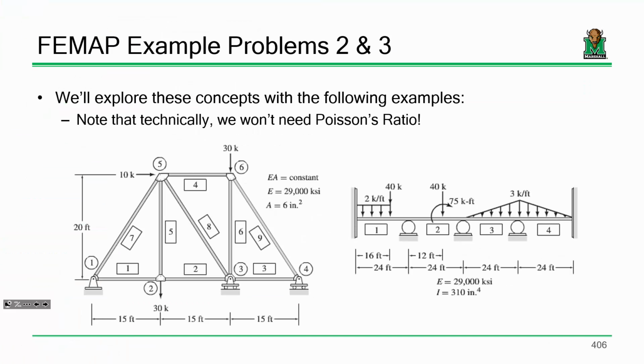All right. So we're back looking at the wonderful world of FEMAP, and if you recall, last time we were looking at this problem, this beam here on the right, and we laid out our nodes and elements and what have you accordingly. One of the different things about how we did this analysis is that we directly hard-coded our mesh, if you will. We didn't create a geometry and then mesh it. Instead, we literally drew in the nodes, drew in the elements, and ignored that geometrical definition and just analyzed it accordingly.